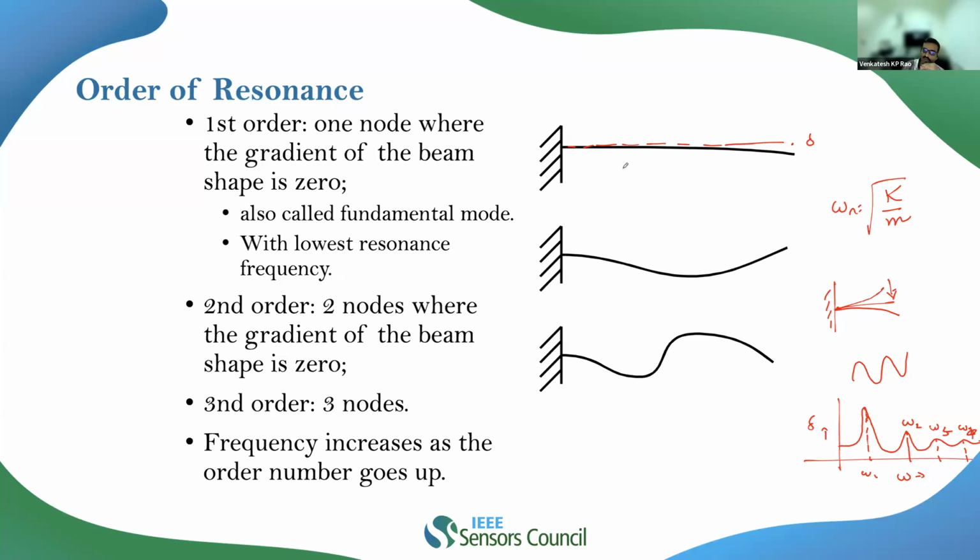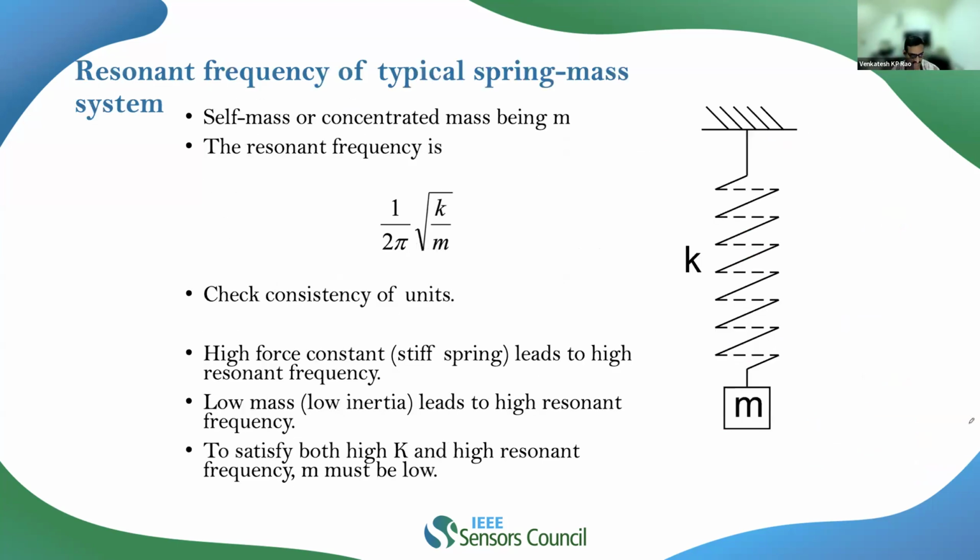At the same time, in this case I have a quarter harmonic. Here I have 3/4 of a harmonic. Here I have many more harmonics. So once I go to the higher modes of vibration, the spatial harmonics will also increase. We get larger frequencies and larger spatial harmonics in the system.